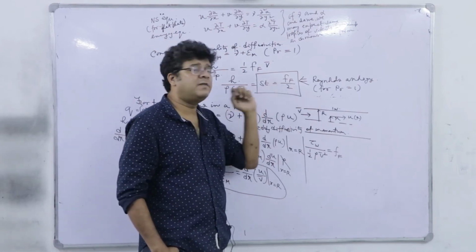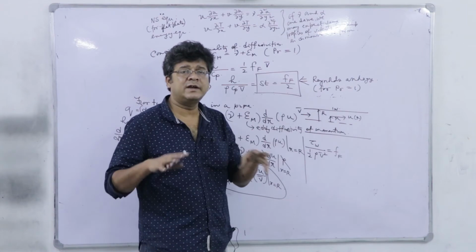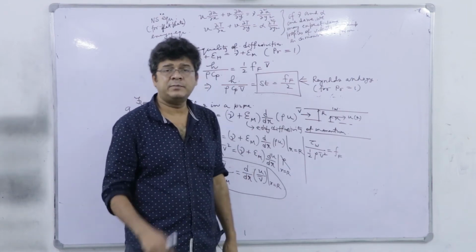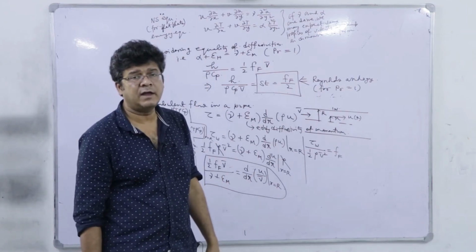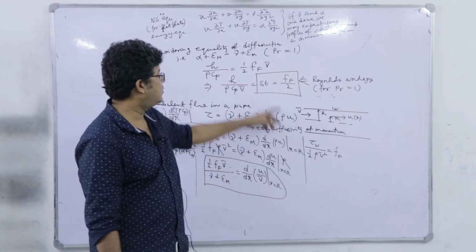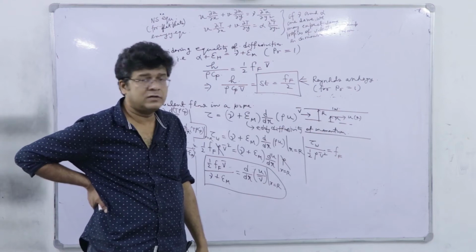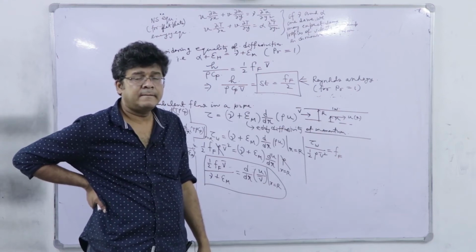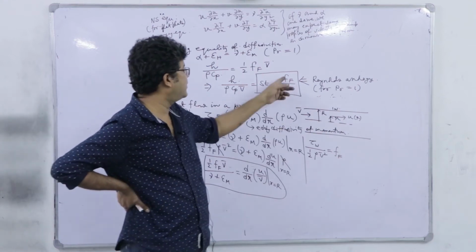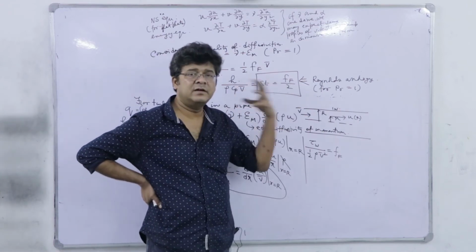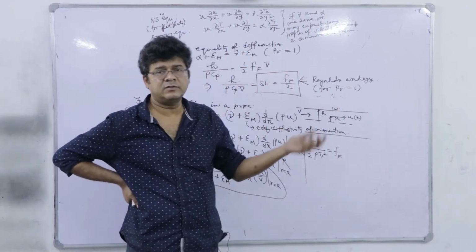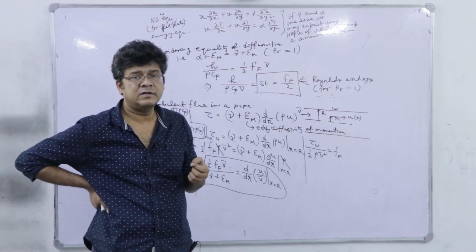And here it is very important to note a contradictory feature: if a pipe is rough, it has a higher value of heat transfer coefficient, because if roughness increases, we know that the friction factor also increases. So, if the friction factor increases, this analogy predicts that the heat transfer coefficient, basically through Stanton number, will also increase.